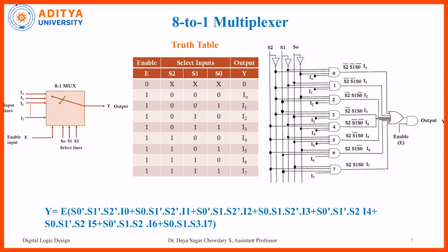Now this is a simple 8 to 1 multiplexer. We can increase the inputs with the help of the selection lines. If we check this block diagram, it is simply a connection that acts like a switch. The output is directly connected to I0 to I7, because there are totally 8 inputs, and there is an enable input also, and 3 selection lines, S0, S1, S2.